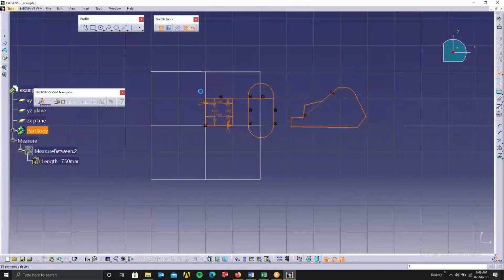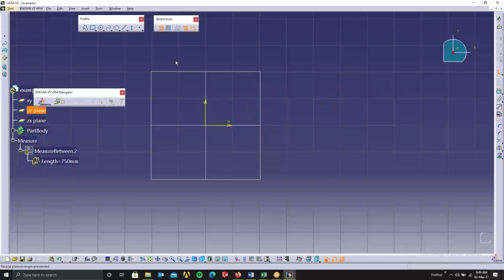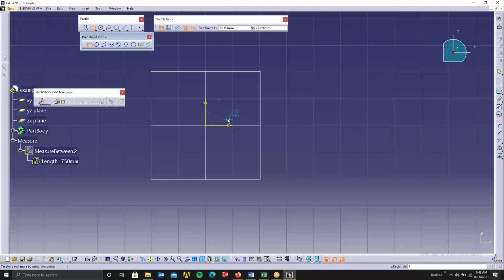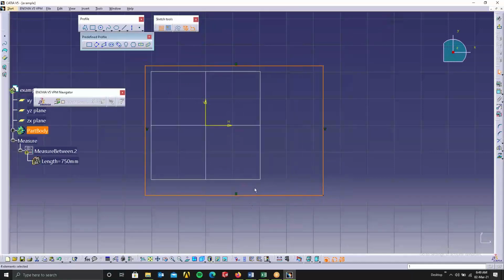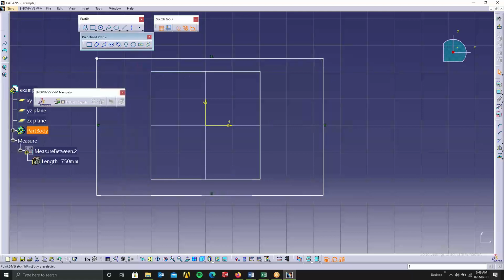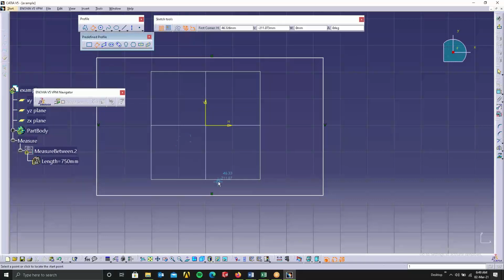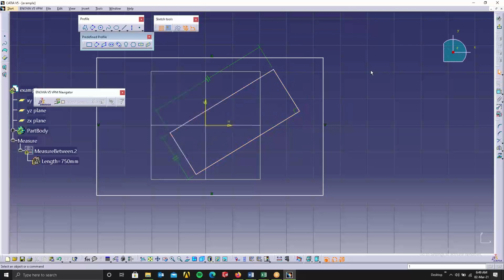So yeah. Next is our rectangles, different types of rectangles. Here we can see a drop down icon is there. If we click that, we have more options. One is our normal rectangle, the two-point rectangle. Click one here, click one here, and you get a 2-point rectangle. This is the basic rectangle that you see in AutoCAD also. Here we have 3-point rectangle, that is oriented rectangle. Oriented in the sense you can create a rectangle at an angle, at an inclination.